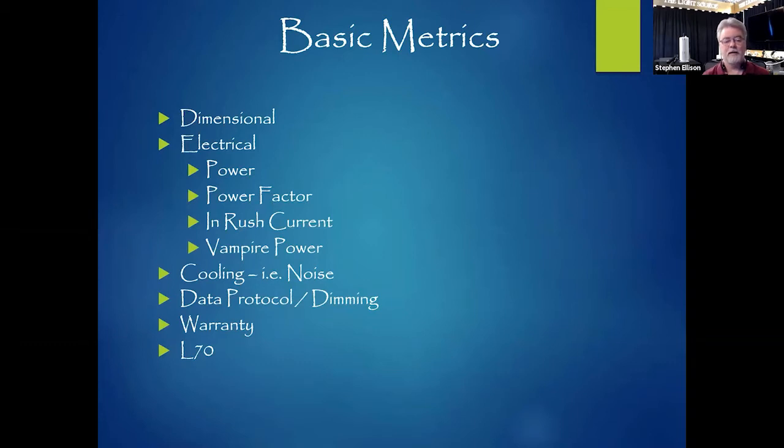We are saving power. There's going to be a thing to calculate that's going to make a difference, because we were used to, if I could, I'd like to dim everything independently. So I would only put one lamp per dimmer, but dimmers were expensive, and you only had so many dimmers in your theater. So you would actually decide, well, I'm going to join a couple fixtures together. And the most you could do was 4 575 watt lamps to get you up to 2300 watts, which would just fit into a dimmer, a theatrical dimmer, mind you, which had a breaker which was designed to handle that full load.